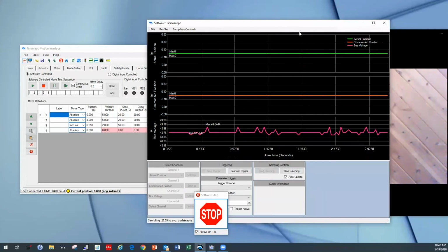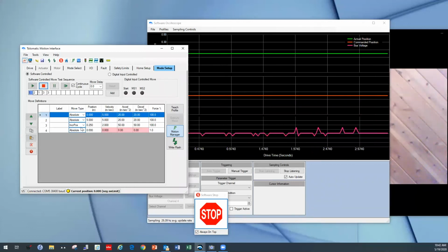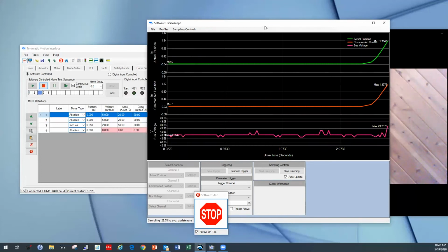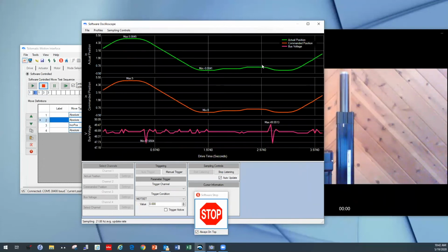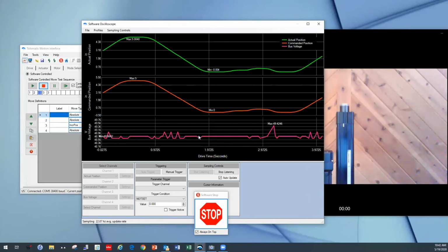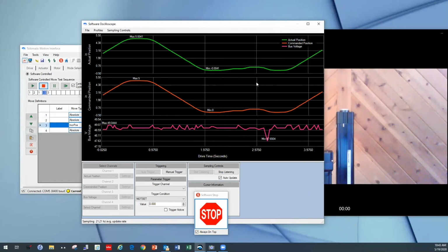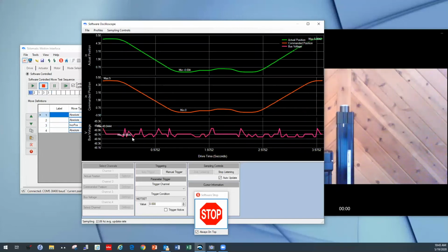And if I do an auto trigger, it's going to start listening. And so now I have this graph going. But if I start the cycle on our table, now it's running out and back. You can see it on the right side, extending and retracting. This software oscilloscope is going to update shortly after the cycle happens, but it's a very rapid oscilloscope to follow. And you can see the commanded position and the actual position are following each other. If you saw some variation in that, then there'd probably be a problem with your position error. Bus voltage is staying pretty flat at 48 volts.